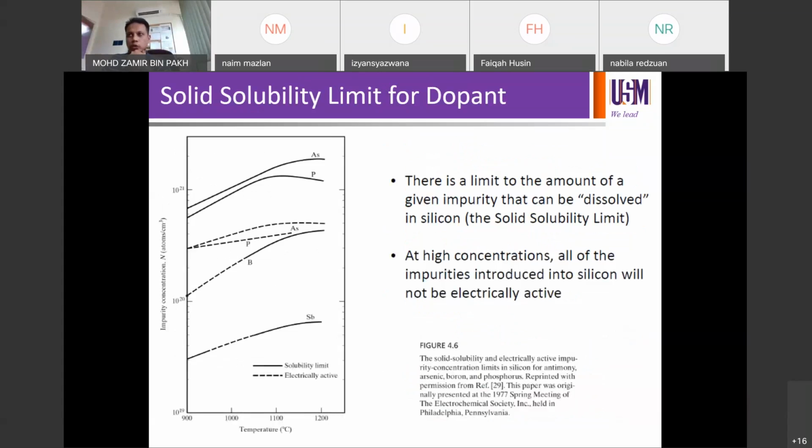Then you know which equations or which profile you need to use for your next calculation. If you don't calculate your DT product, you wouldn't know. So you need to know the DT product first. Then only you can decide, for my next calculation, I need to use the error function or I need to use the Gaussian profile. If you don't know, you'll probably end up with wrong equations.